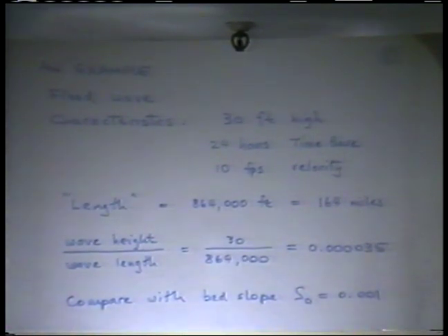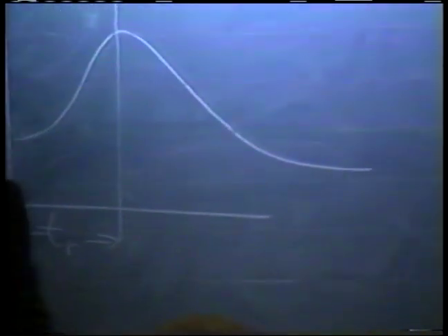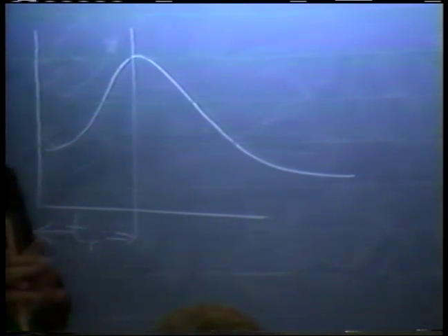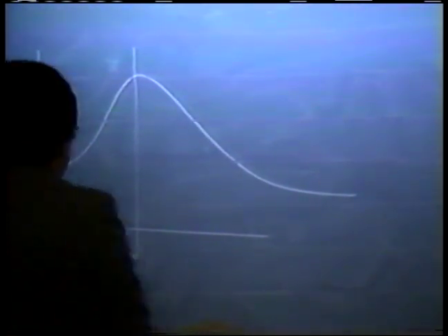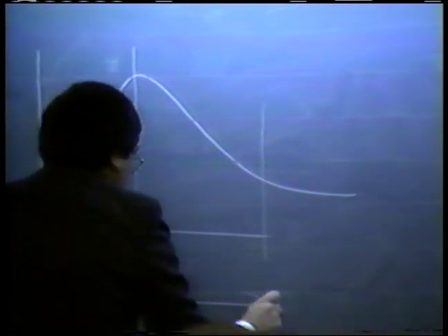Now the time base, for those of you that are not in the hydrology, the time base is a hard thing to pin down. Many people can talk about time of rise, but very few can talk about time base. But I have to in here because I'm going to make a mathematical comparison. You have a flood wave, okay, and the time of rise is very well defined. But the time base is not very well defined because of the recession and the fact that we very seldom can accurately pinpoint exactly where the recession is going to finish. But for practical purposes, we could say if it comes back within, say, 1% of what it was before, I can say that this is going to be the time base.